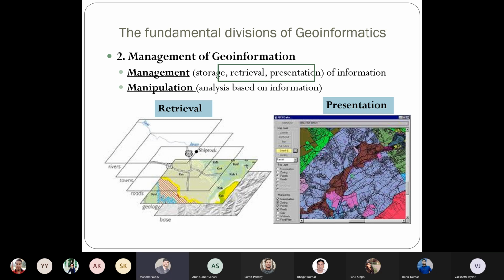In the image itself, you need to identify the ground pixels first, and you get the digital elevation model. The digital elevation model tells you, if the flood originates from some water source, let's say a river in the city, how quickly that flood spreads in the city, which is decided on the basis of the terrain of the city.